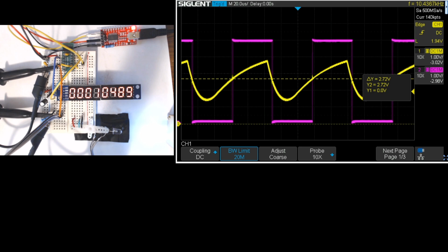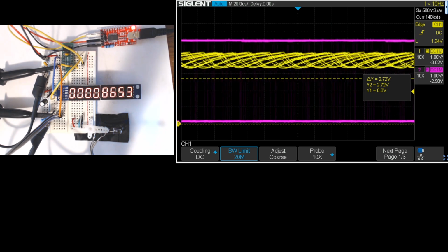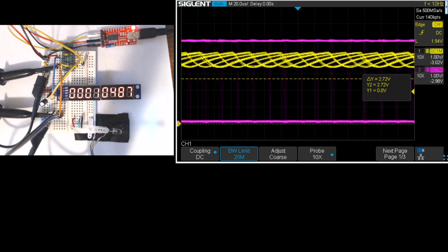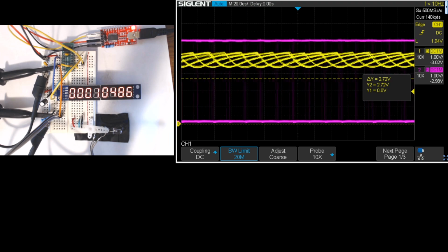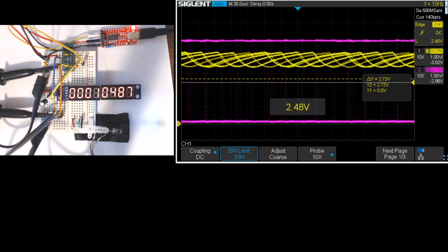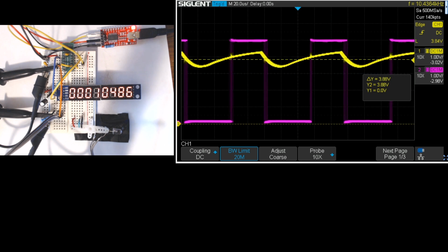So I can make it more challenging and get the flashlight kind of completely out of view of the display, but make a weaker signal. And we can see that the counts are still accurate from the ATtiny. And let's adjust the trigger on the oscilloscope. The oscilloscope's measuring about 10.4 something kilohertz still, so they're still consistent. And now the threshold is up to around here. So that's Y2, about a 4 volt threshold. So the threshold's changing as I move the flashlight around.